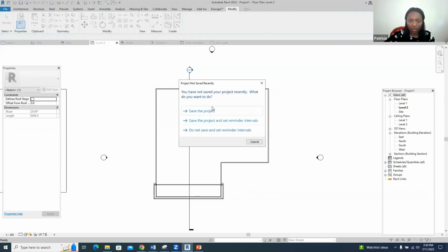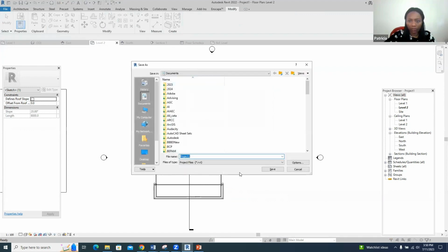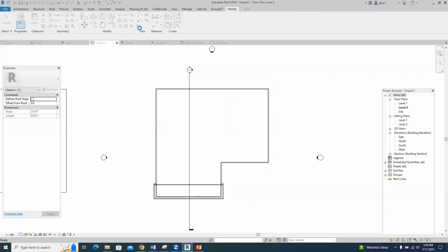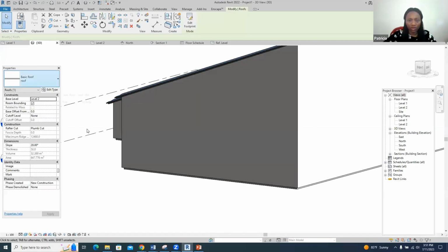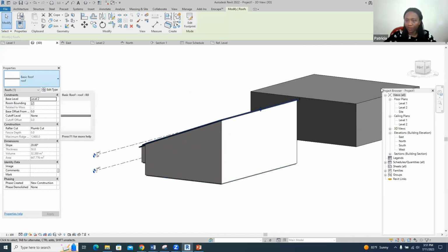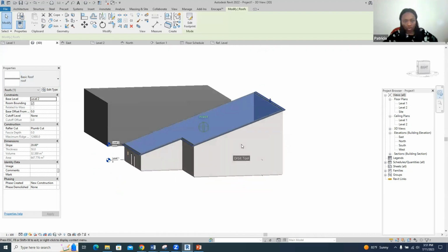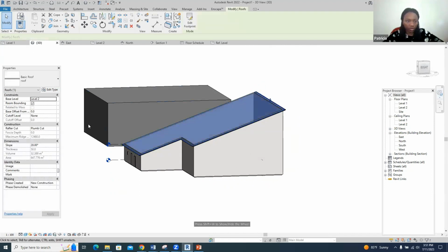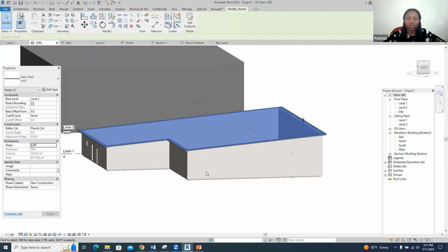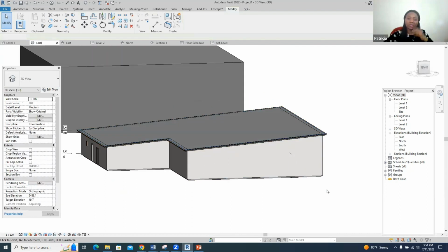Once you're done, check the green mark and it's a reminder to save the project at some point. So let's see what we've done here. Oops. So this is what's happened with all that slope. So we can set the slope to a side. We're sloping to one side now. I think that the angle is too much for this kind of thing. I will make it 5. And then you can see, you can really play with the roof by removing or adding the slopes on it.